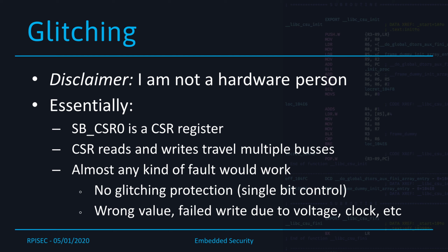So if the state is that the boot ROM should be locked, instead of having a single bit that you're just checking to see if it's a 1, then we're good, and if it's a 0, well then we're gonna do whatever, instead you'll have large whole words that need to be set to any value in order to disable the boot ROM.